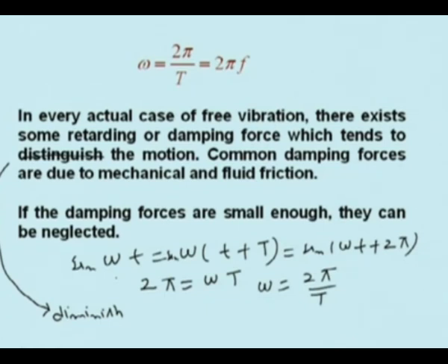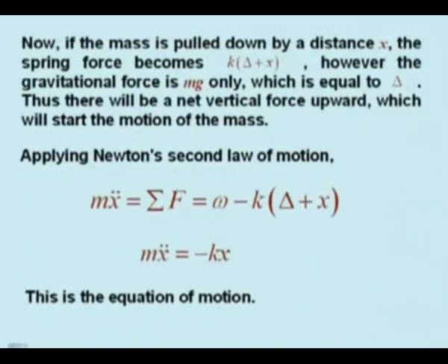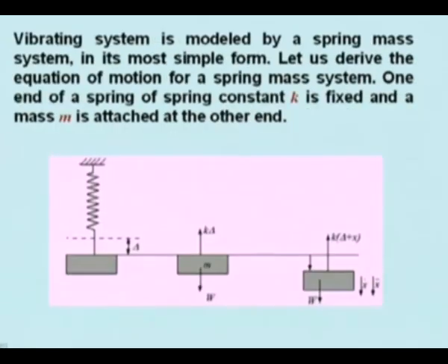Therefore, if the damping forces are small enough, they can be neglected, because they are very small. For some time, we can study the motion for a considerable period, and the damping can be neglected. Moreover, from the designer's point of view, it is conservative first to study the motion without damping, and after that we see what is the effect of damping. Damping will have an effect of reducing the vibration.